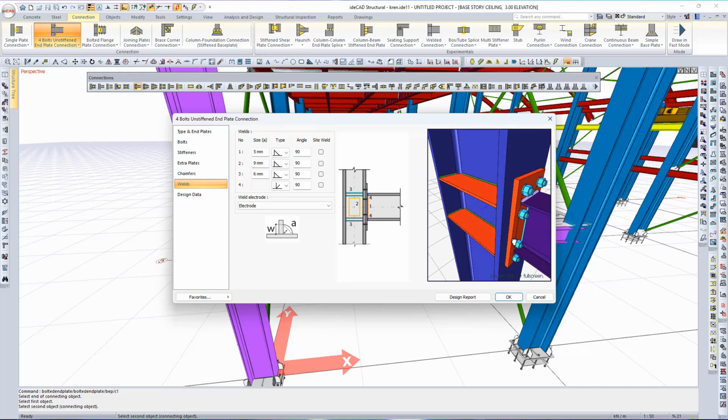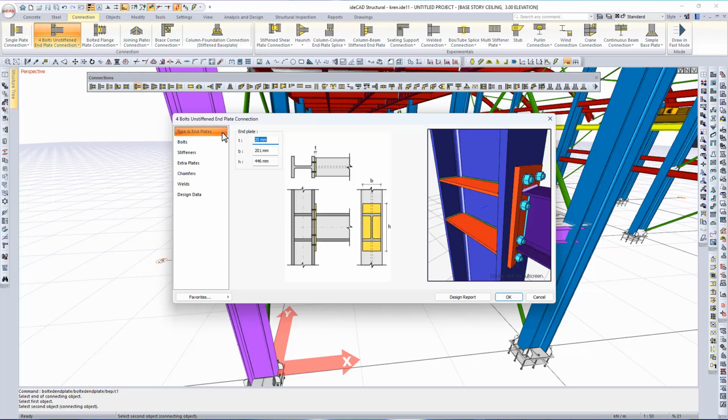One important note, specific seismic detailing requirements, such as cross-sectional limits stated in seismic codes, are not enforced during connection generation. These requirements must be checked from the design reports after analysis. If any insufficiency is identified in the connection design report after running the analysis, it is solely the engineer's responsibility to address and resolve it by modifying the structural design. The purpose of this feature is to ensure the generated connections are adequately safe under the anticipated design loads. However, you are always free to adjust or reduce the connection capacity if necessary for your project-specific requirements.